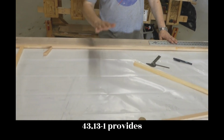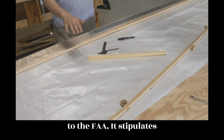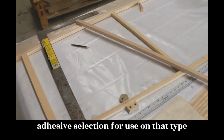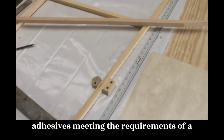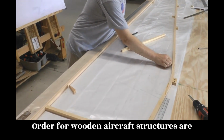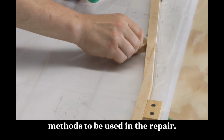AC 43.13-1 provides information on the criteria for identifying adhesives that are acceptable to the FAA. It stipulates the following. 1. Refer to the aircraft maintenance or repair manual for specific instructions on acceptable adhesive selection for use on that type aircraft. 2. Adhesives meeting the requirements of a MIL spec, Aerospace Material Specification, AMS, or Technical Standard Order, TSO, for wooden aircraft structures are satisfactory, provided they are found to be compatible with existing structural materials in the aircraft and fabrication methods to be used in the repair.